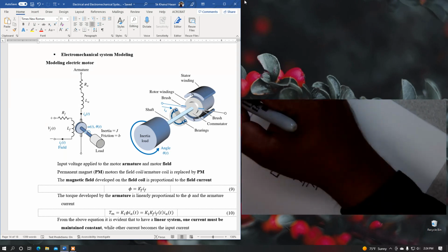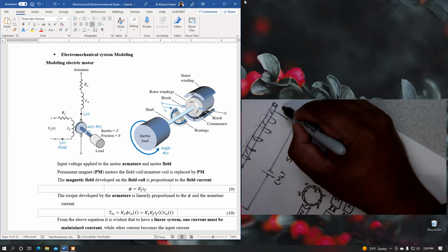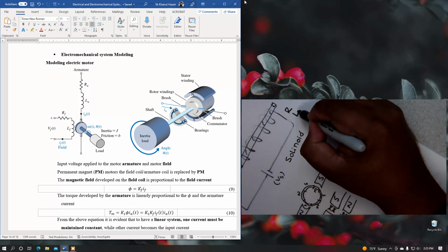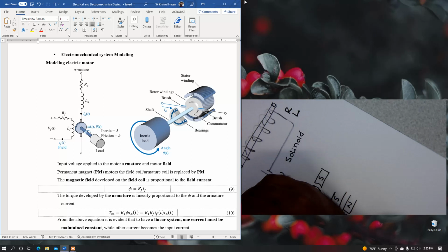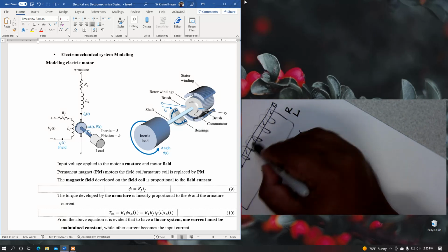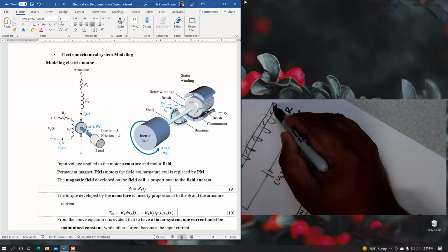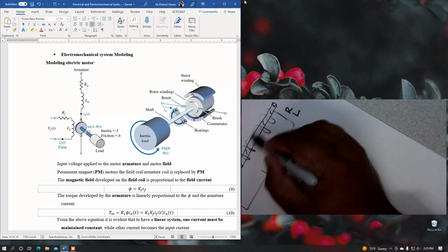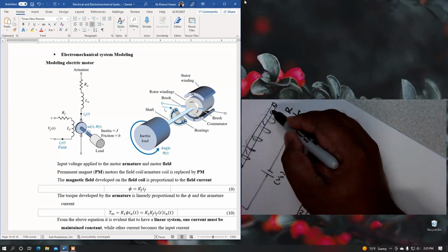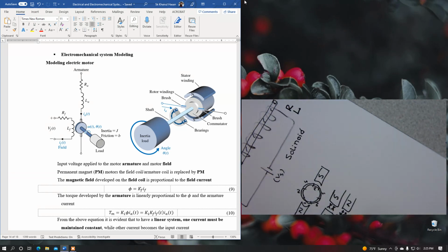Now, this coil has some resistance and also some inductance. And a good question is, why do we place the core or iron rod inside the solenoid? We place it to produce a strong magnetic field, because the produced magnetic field also depends on the material inside the solenoid. That's why we place the iron rod or iron core, a ferromagnetic core, right?